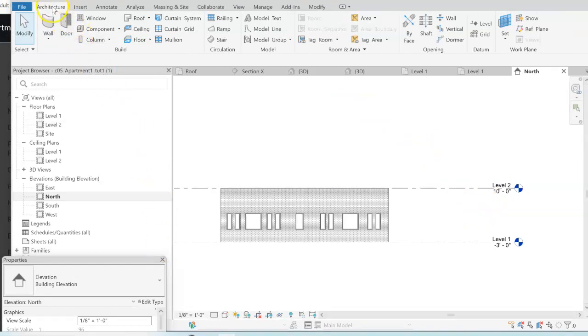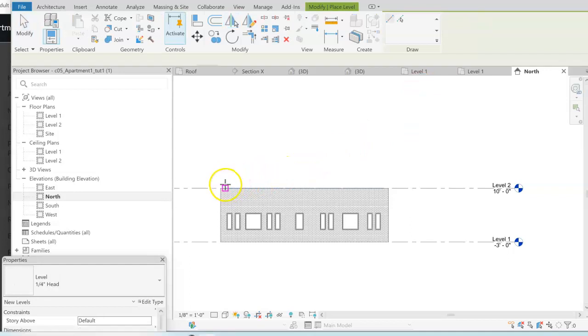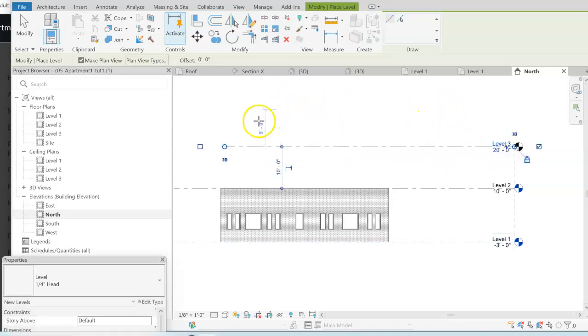Using the architecture tab, I invoke that, and I can go and find that I have levels and grids available to me. I'll choose level. And I will line it up, and I think the book has it at 10, so I'm just going to drag 110, and then it creates a level that I'll put out here. Use that indicating line up to line up things, and keep on going. Right? I'll march another one up, and I can adjust these later, as with most things in Revit.